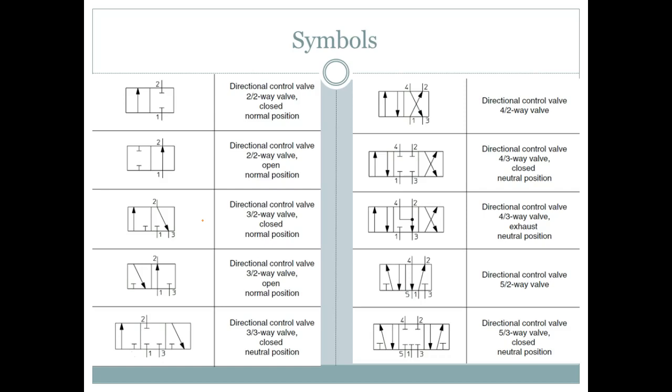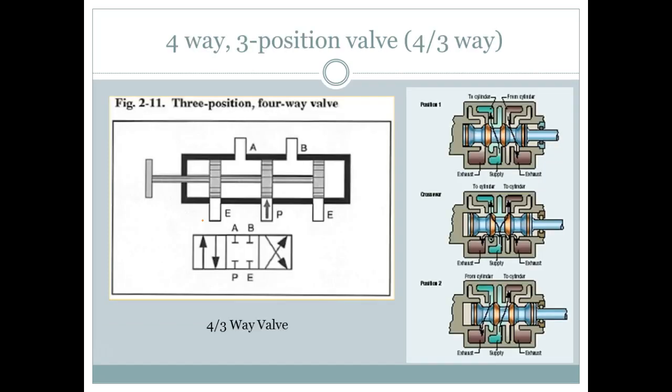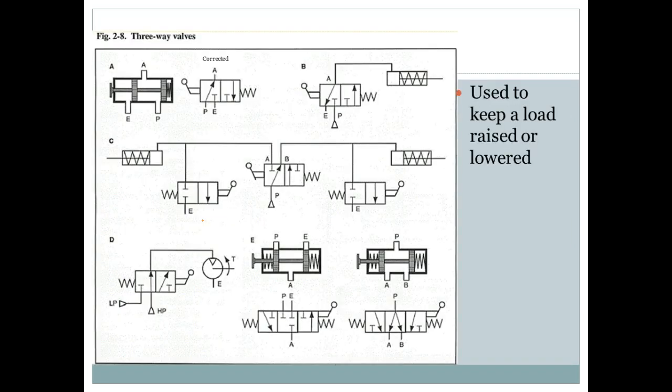If we have a spring on it, it's usually opposite of the spring, and that's why a lot of the diagrams in the textbook are wrong. Like this one right here is wrong. Why is that wrong? And this is out of the textbook, guys. I don't know who did this. What's wrong with that? The spring's on the right, but they have your ports on the left. So according to the port identifiers, they're showing it on the left, but that spring's going to push it to the right. Y'all understand what I'm saying?